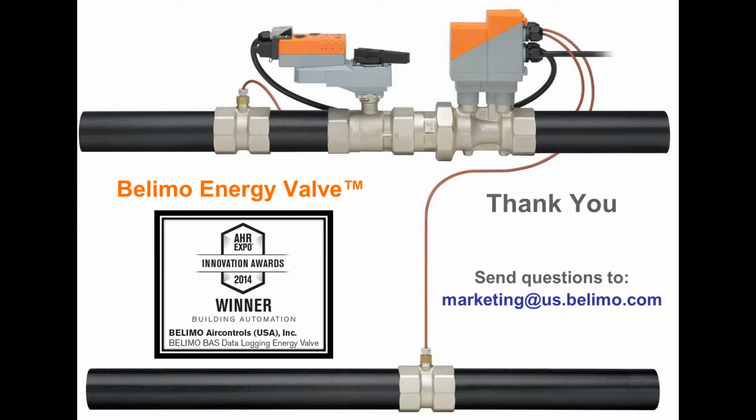The second part of that question was what, Michaela? I also assume that this will operate in standalone mode with no DDC control system. Okay. So in general, if you don't connect the DDC to the energy valve, there's no way for it to modulate based on any input. In other words, it only takes a 0 to 10 or 2 to 10 or 4 to 20 input, if you do it that way, and that needs to be generated by something.